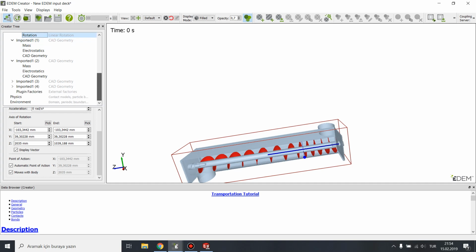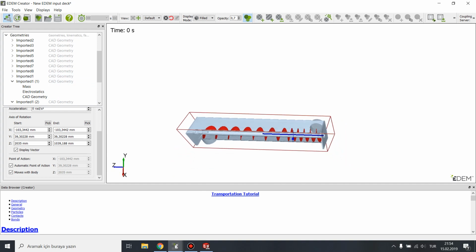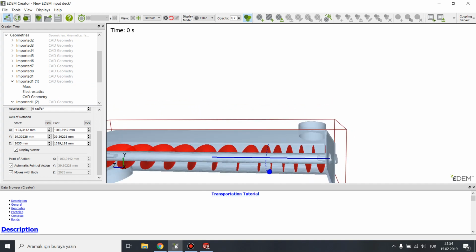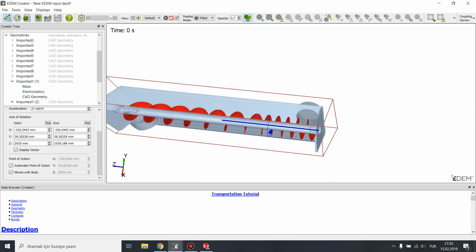So okay, next thing is I need to define my inlet. It is a bit problematic because, as you can see, my inlet is here, but this geometry is empty. It is a hole actually, so I cannot select this surface because it is empty. So I need to define a surface in here and define it as inlet.